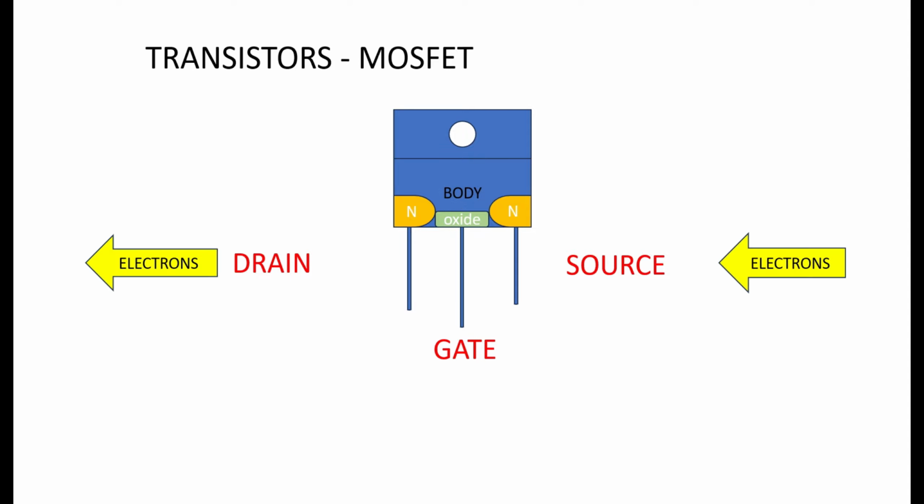So like the BJT, voltage enters in through the source, goes through the transistor, and then it comes out of the drain, right? But in the case of the MOSFET, the conductivity between the source and the drain, around the barrier, allowing it to block or allow electrons through, is controlled by an electric field that forms around the oxide layer when we apply electricity to the gate terminal.